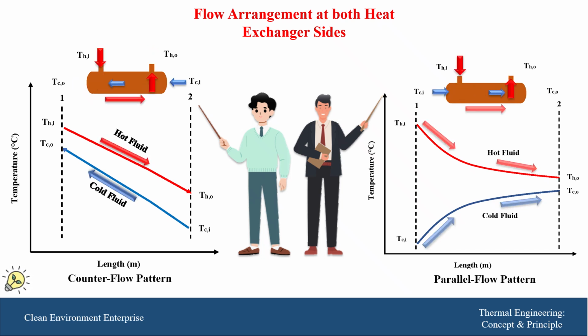In general, all heat exchangers are preferred to have a counterflow. In the counterflow, there is a uniform temperature distribution and it provides a good temperature difference between both fluids, so it is more efficient than the parallel flow pattern.